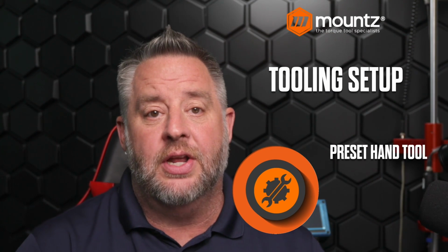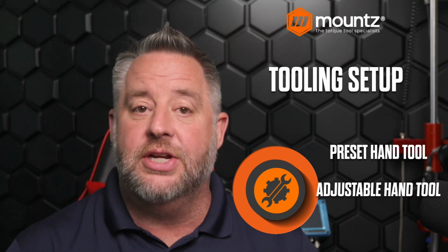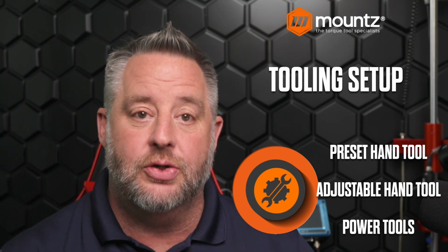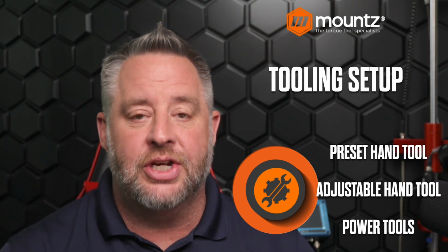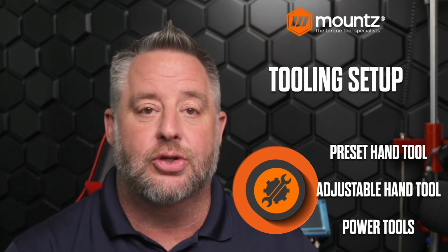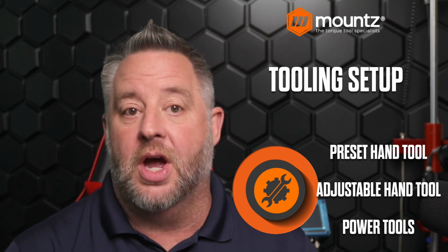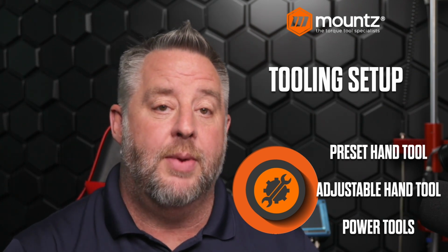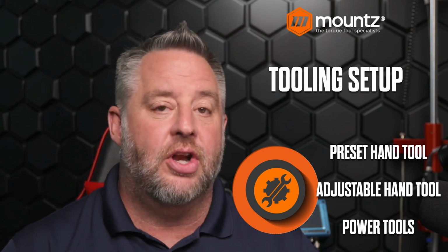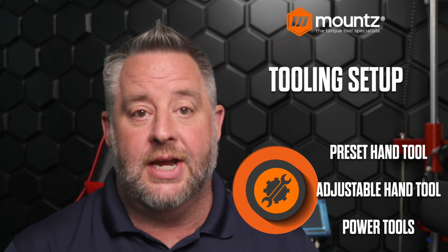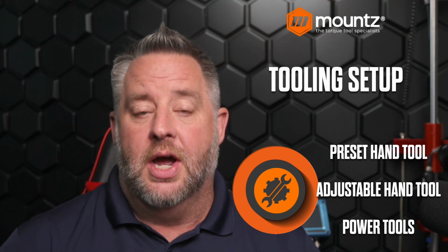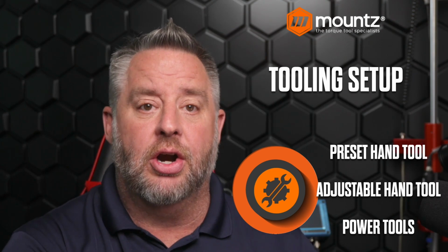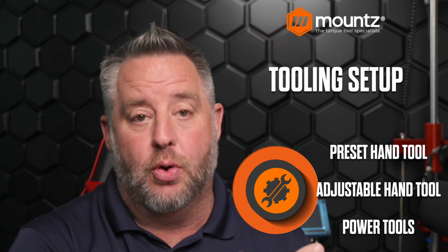So when we look at the tool setup, what we are basically doing is if we were to remove one tool from a work area and put it into another cell or another application, we will need to make adjustments to the torque value for that. And that could be done with a preset tool. We can also do setup on an adjustable hand tool. We want to make sure that we're consistent through the range of the tool. And this can also be during a power tool setting as well. Could be an air tool, could be an electric clutch torque screwdriver. And that would be when we would be using our torque analyzer at the tool setup portion before the assembly process.